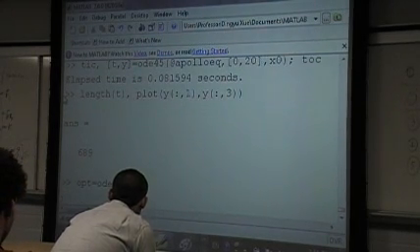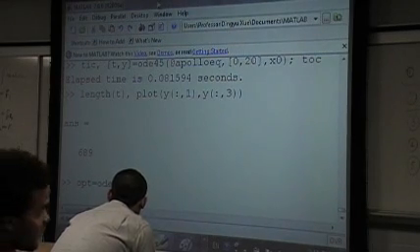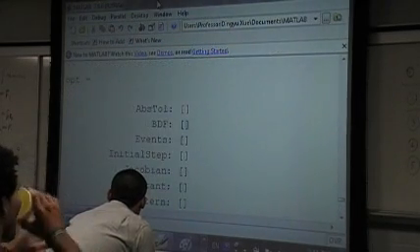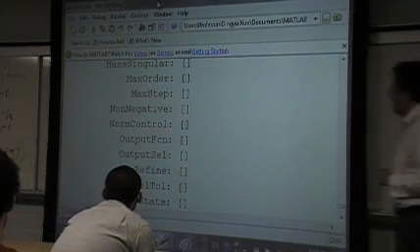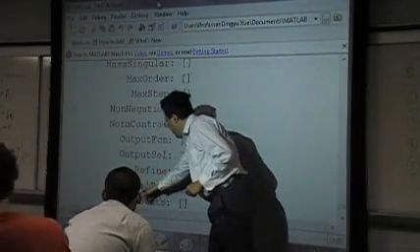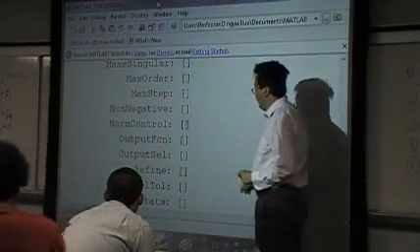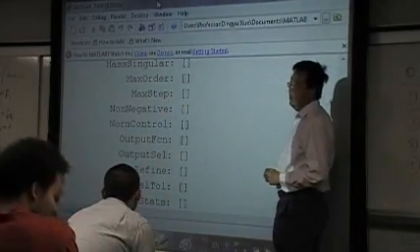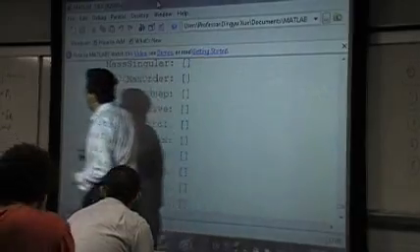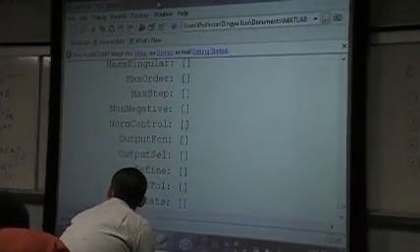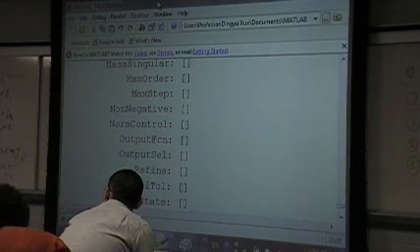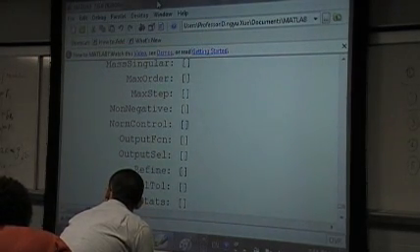The template has many components, and the most important component here is RelTol, which means relative tolerance. It is similar to the epsilon here. The default is 10 to the minus 3. It's too large. We can set it to a small number.